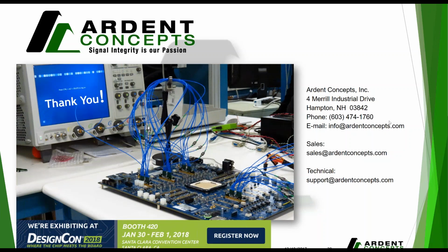Awesome. Thanks, Ben. Oh, another good one. Board footprint materials. For eval, what do you request? What do you use for your eval board? And also, when you're making production and test boards, what do you use? We use ENIG on all our test boards and our eval boards. We recommend to our customers to use hard gold. Obviously, with our compression mount technology, the contact is constantly making contact with your signal pads or what have you. So a hard gold is going to give you a longer lasting finish. But the truth of the matter is, with our ENIG, we have cycled that up to 1,000 times and had no problems with the repeatability whatsoever. It's just we've always recommended hard gold, but for all our own internal use, we use ENIG.